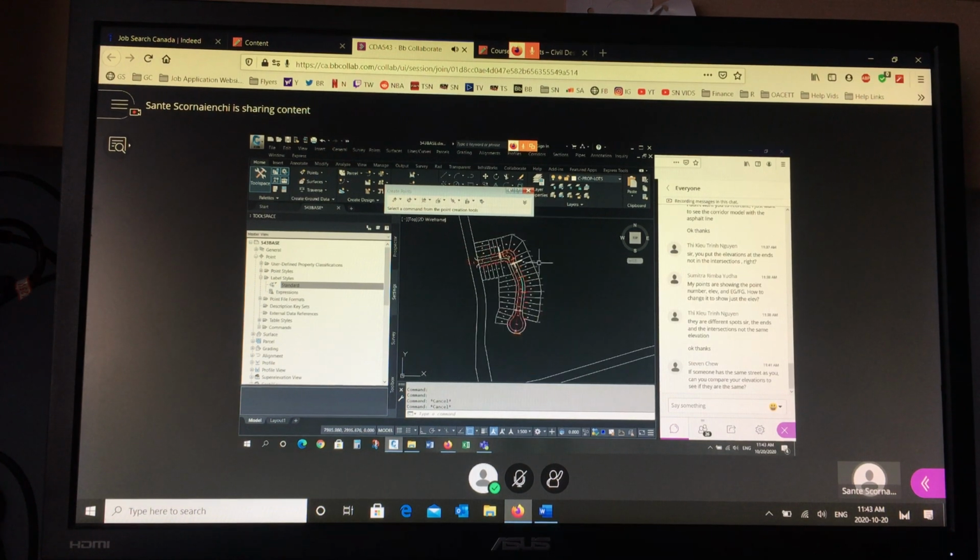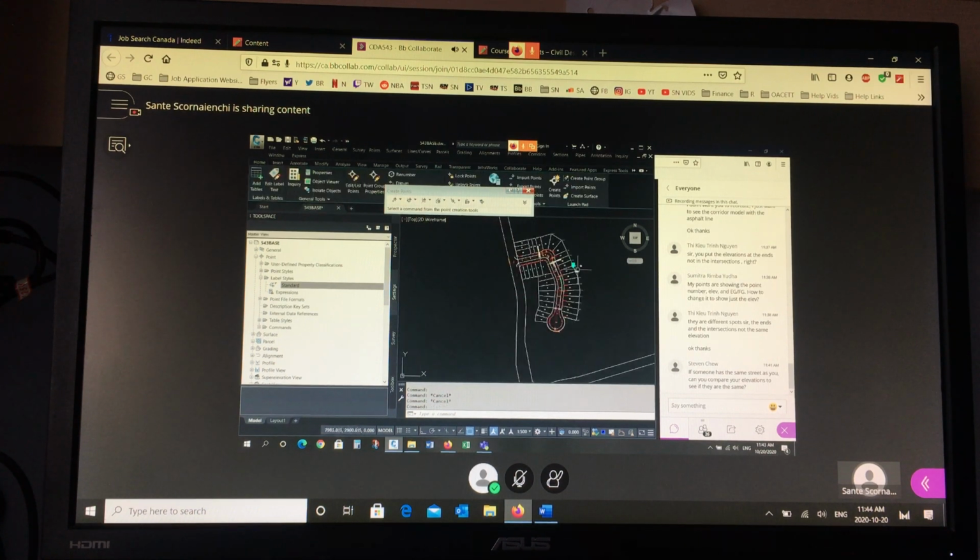So this is basically what you need to have done for Friday. It doesn't take long to produce the points. It doesn't take long to get the elevation for the points. The time it takes to create that corridor surface model is what's important. If you don't do the corridor, you can do the front lot corners before you even start your design. You could do that right at the beginning because the existing ground surface is already available from assignment 1.